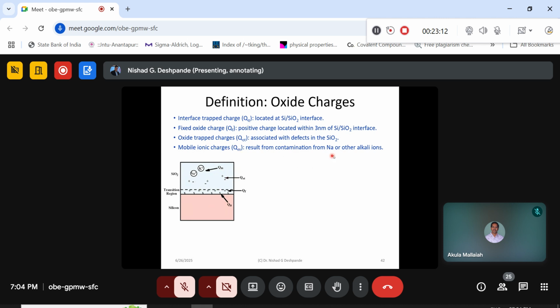This is one part. The other part is what? The other part is that purposefully you are trying to introduce contaminants into the surfaces. That particular part we call ion implantation processes. So you can go and put an ion forcefully into these layers. Now that ion can possibly form mobile ion charges there. Okay, so that is how the mobile ion charges are being considered.